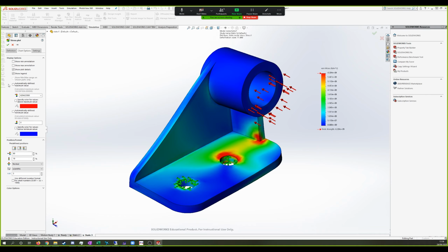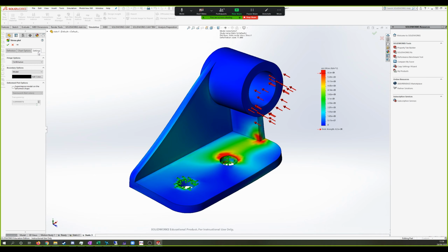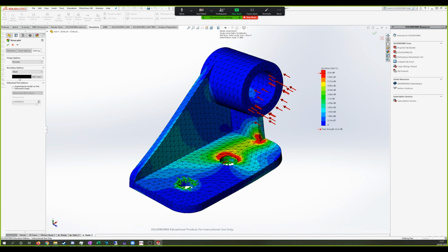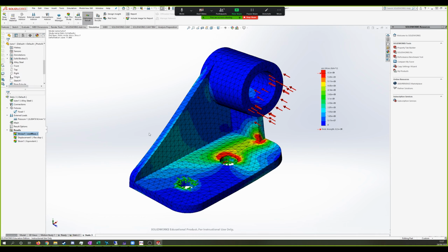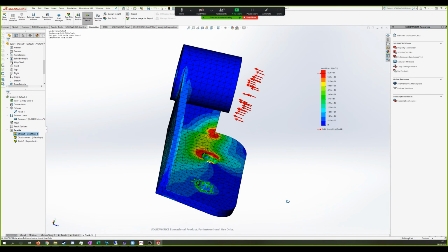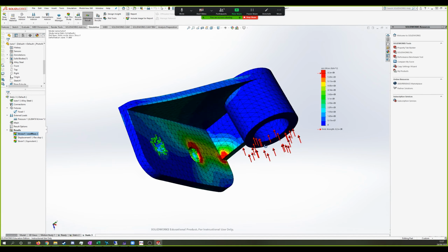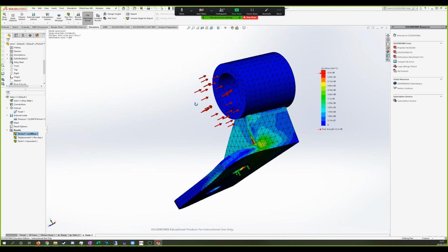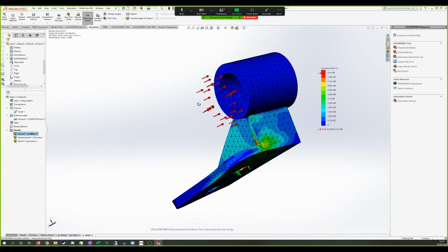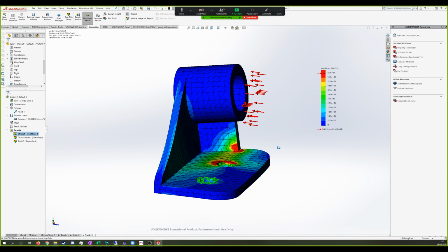Change scientific down the bottom to general, then go to settings, and where it says continuous, change that to discrete, and then change your boundary options to mesh. Then tick the show or hide mesh button. Why didn't that update? It didn't change your scale on your graph.